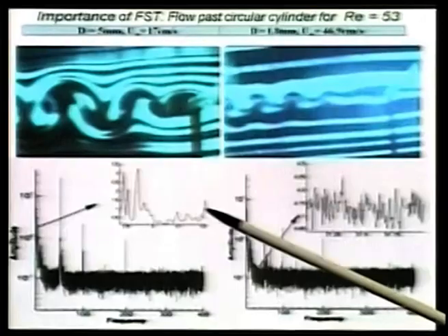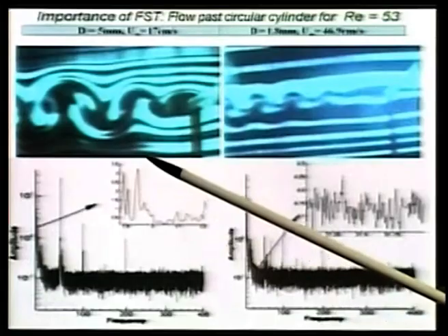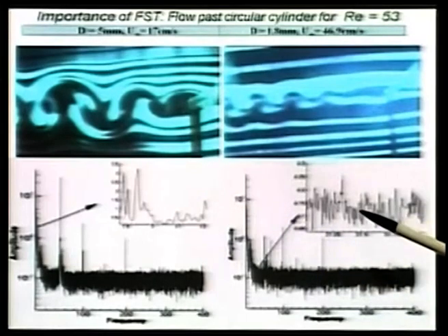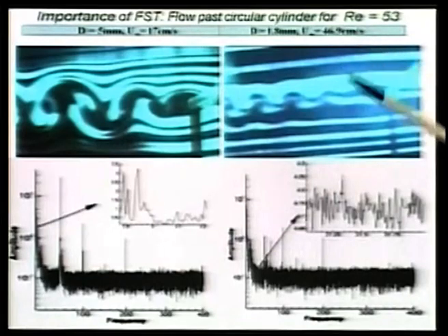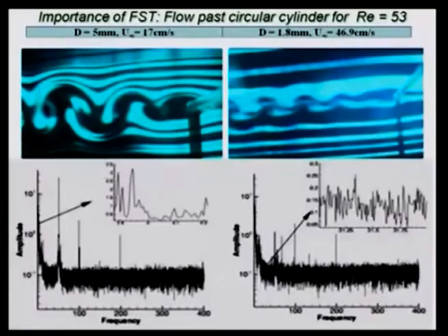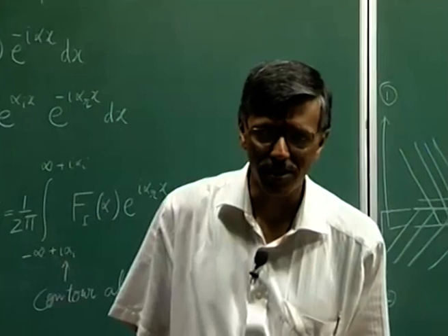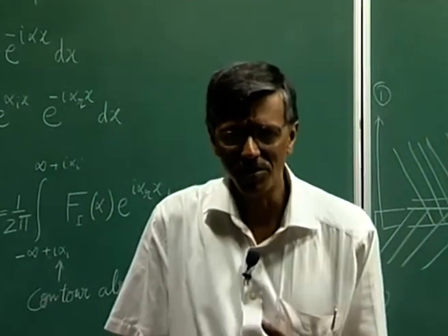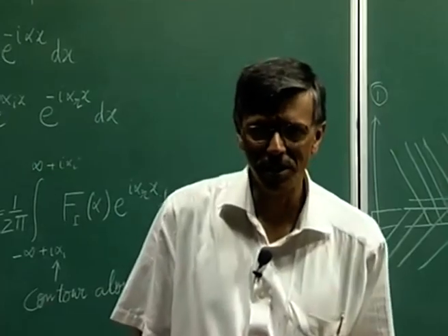So, at the Strouhal number we have the background disturbance that is the most robust. In contrast, for this higher speed case, I get a value about 10 times smaller at the Strouhal number. This tells you a very clear story: if you do not have the cause, you do not have the adequate effect.